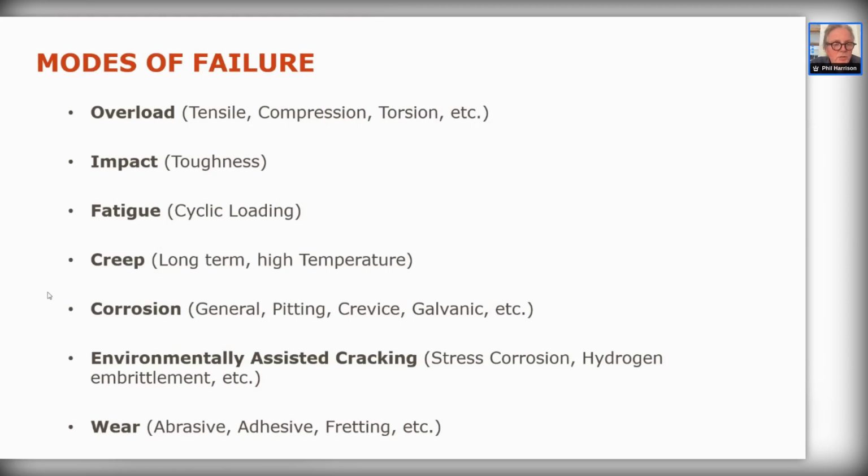We have general overall corrosion, mainly when we see steels, when we see a rusted steel, that's general corrosion. We have pitting corrosion. Generally, this happens on materials which are protected by a passive oxide film, for example, stainless steels and aluminium alloys. You get discrete areas being removed, and you get perforation or permeation of things through the thickness of a material without much weight loss or anything.